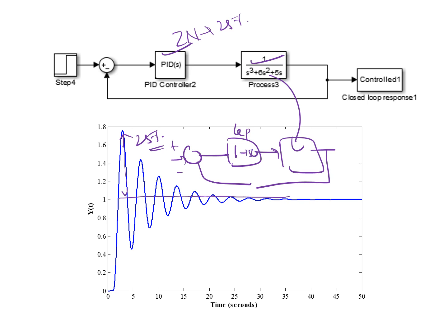And for each and every value, check whether you are getting sustained oscillations. But from the theoretical calculation, we found that when it is 30, sustained oscillation is there. So you have to calculate this Pu. Theoretically, you have to substitute s equal to j omega and find out omega. Then the ultimate period is 2 pi by omega. Okay. So this is theoretically, and this is in MATLAB.